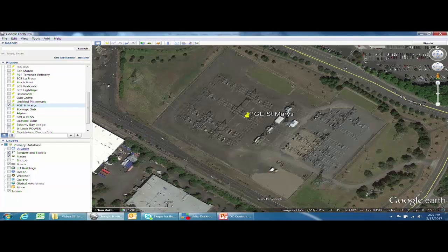After much hand-wringing and deliberation, it was going to be a big problem, because if we decided to reconfigure this, we were going to have to slide these transmission lines down, and you can see that the existing transmission tower could not support moving these lines further down. We would actually have had to put in another big double circuit 230 turning structure. So again, after a lot of deliberation, we decided to simply leave it as it is. And we figured that the chances that that breaker would ever go into breaker failure were amazingly remote.